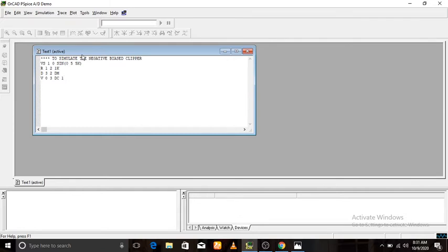And for the diode, here is a command to model a diode. We use the semiconductor diode basically. So the command is .model, the name of the diode DM, and D is the parameter. We have some parameters like saturation current IS equal to 1e-10, and the emission factor N equals 1.